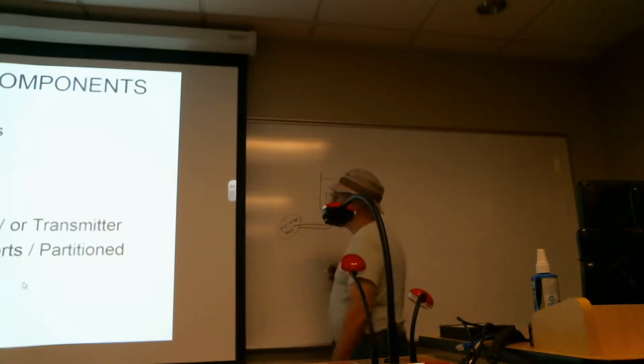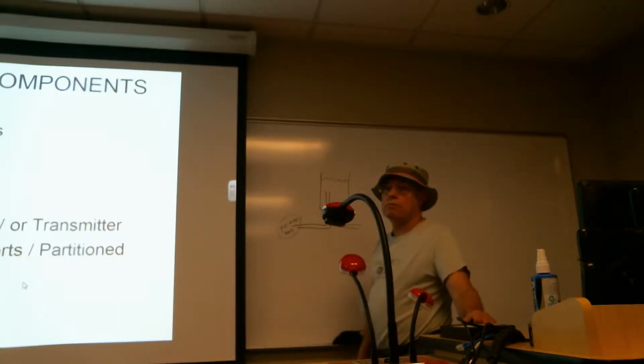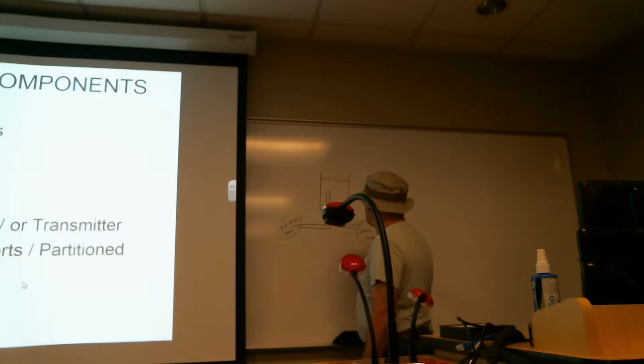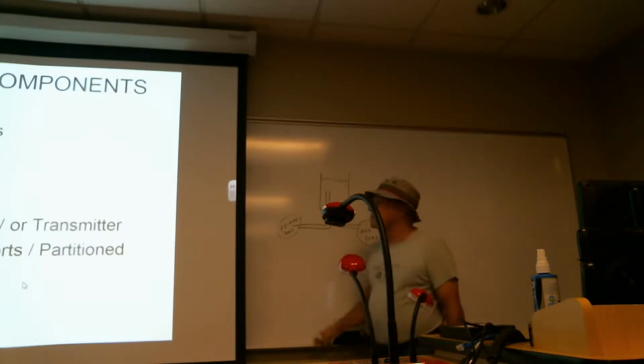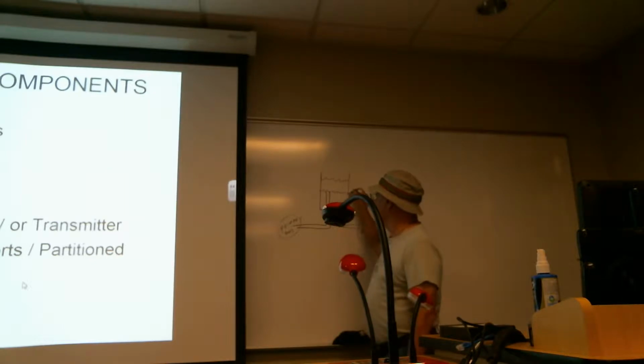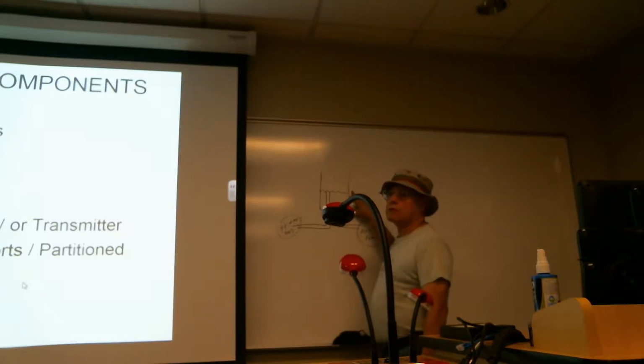And our auxiliary pump, whatever it might be, hand pump or electrically driven pump, we'll call this one the auxiliary pump. Right here. So the idea is this: when the level of fluid gets down to the standpipe, by nature the primary pump is going to be starved of hydraulic fluid. So the level gets down to here. Well, what that does for you by having the standpipe provides for the quantity of fluid that's beneath the level of the standpipe to be only available for the auxiliary pump.